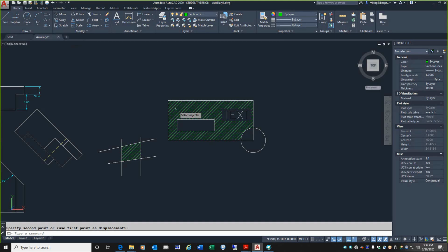So I'm going to go back to move, and I'm going to pick on the, I didn't click quite right, click right in between the hatch lines there, and I'm going to move this where some of this goes out beyond the shape. Okay, so you probably wouldn't have expected it to hatch in this outer area, and that's just kind of weird. So what we've done is we've gone beyond the hatching intelligence. I'm just going to do an undo. And if you needed to move this half out and half in, you could just simply erase the hatch and redo it.